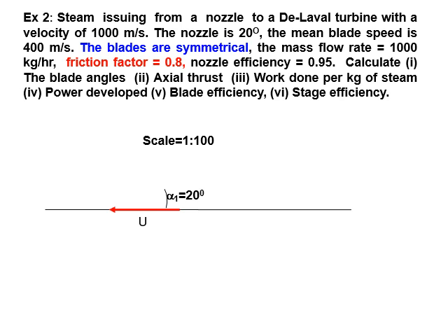On that alpha 1 angle line, mark the V1 value, the absolute velocity at inlet. V1 is equal to 1000 meter per second, and according to the scale this value is equal to 10 centimeter. So now mark the 10 centimeter line on that. Now we are getting the V1 length. Then join the other point of U with the intersection point of the V1 line. That is known as the relative velocity at inlet.